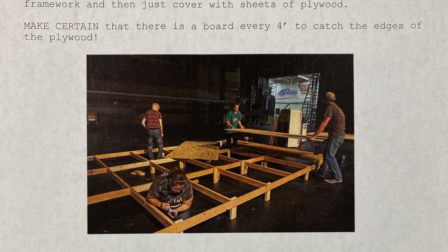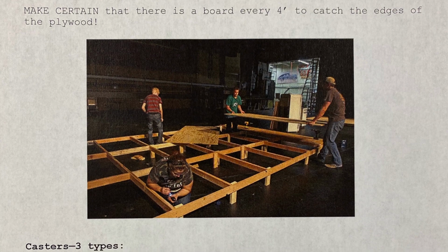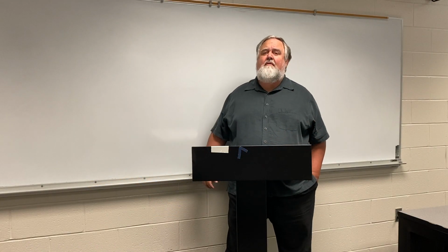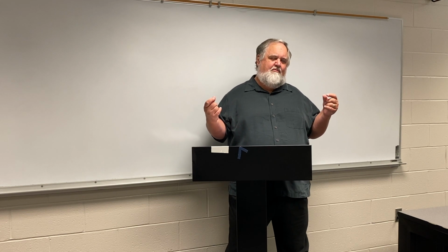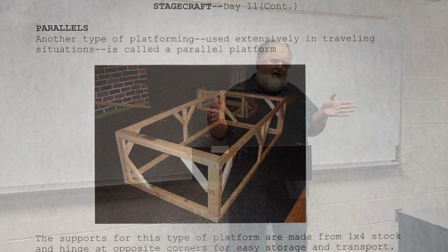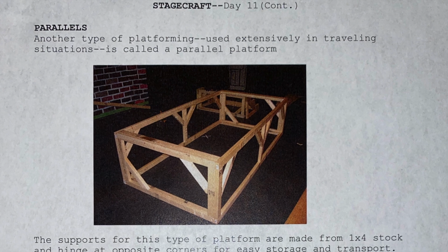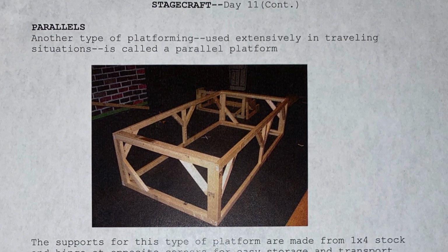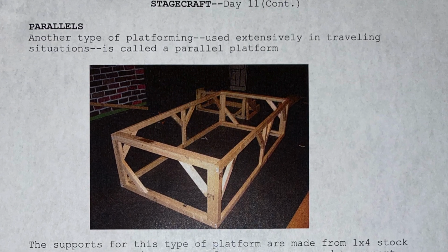There's also a thing called parallels. Parallels are great, especially for tours, because everything is hinged and they fold up very nice and neat, and then all you have left is the tops all pop off. Because of the way the top is, you add a little piece of wood, 1x4, and when it fits square, it sort of sinks in, holds the parallel square, and you really don't need a whole lot of attachments usually.